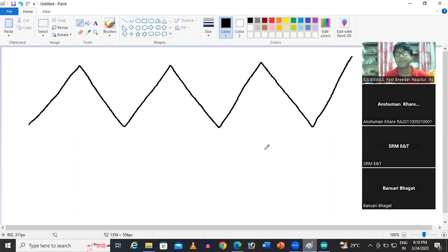Whenever we work on power electronics applications, we need phase correct mode because we need to provide the dead time. That also we will learn now. This process is called up counting and this process is called down counting. Say your output compare register value is somewhere here. Up counting, the match occurs here, so your pulse will become high here and keep on high.